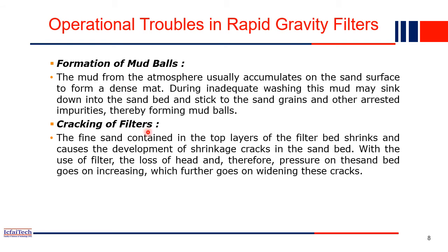Then another problem you will find is the cracking of the filter. The fine sand coating on the top layer of the filter bed shrinks and causes cracks to develop in the sand bed. With the use of the filter, the loss of head, and therefore the pressure on the sand bed, keeps increasing, and thus the crack size also increases. You will find these cracks initially as micro cracks at the top of the filter medium, and gradually the crack size will increase as the pressure increases. That also we have to take care of.